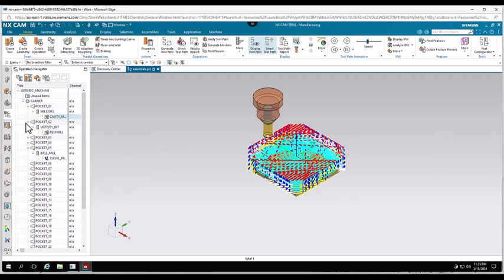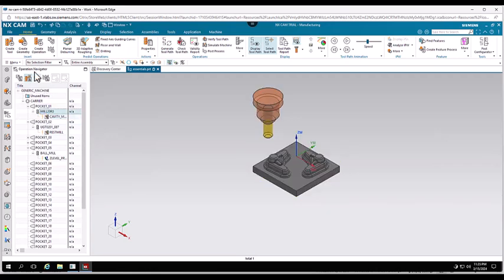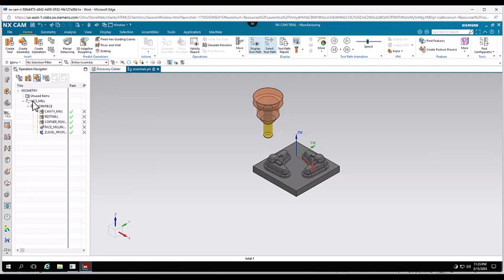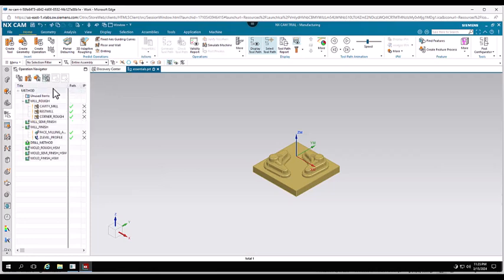Next is your geometry view. Now this is where you set your machining settings that define your home base, as well as other geometry settings that NX uses to create toolpath on the engineering model. And then finally, you have your machining method view. Now this is where you can create global settings for feed rates and other specific machine methods that you want your operations to inherit and follow. And we'll go over more of this in later videos.